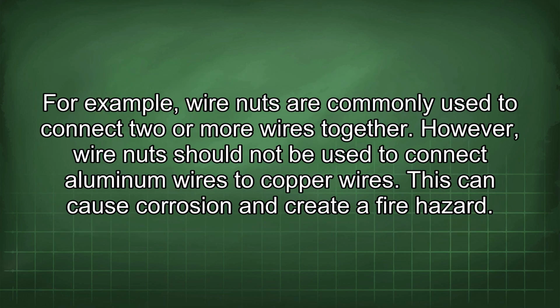For example, wire nuts are commonly used to connect two or more wires together. However, wire nuts should not be used to connect aluminum wires to copper wires. This can cause corrosion and create a fire hazard.